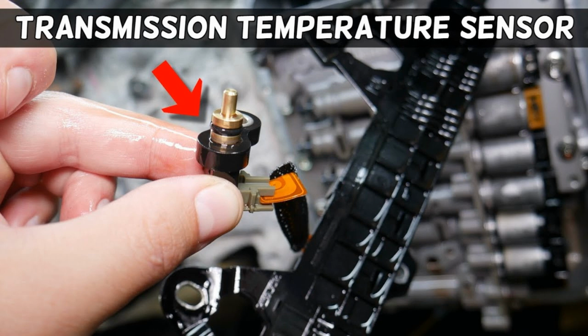Monitoring transmission fluid levels. Check transmission fluid levels regularly, following the recommendations in your owner's manual. Make sure the fluid is clean and complies with the manufacturer's specifications. Inadequate levels or contaminated fluid can cause temperature problems and trigger trouble codes such as P0711.